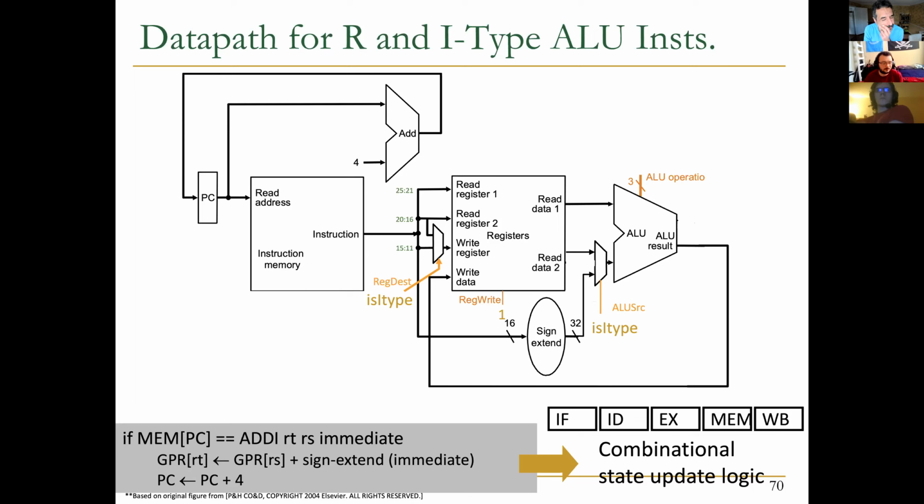How exactly? I think it worked a lot better in my head. So if you add a flip-flop to do what? Add a flip-flop to control 2 different inputs. If you only ever want one of them out at once, use a flip-flop to control if you want sign extend or read data 2 to go to the output. That way you don't ever have both, but you can have one. You can control the flip-flop similar to the multiplexer. Where exactly do we need to add the flip-flop? Yeah. You would add them in the same locations as the multiplexers. I think in my head I just built multiplexers with flip-flops. That's right.